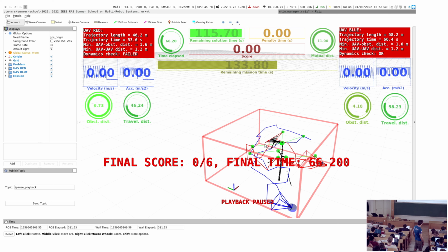So our system can output any command you need. If you need velocity reference, acceleration reference, attitude rate reference, even the motors, we can do it. It just depends on what the system on the other side can accept. For flying with custom SLAM and localization, you sort of need at least the attitude rate as a reference signal to be able to control the attitude completely yourself.